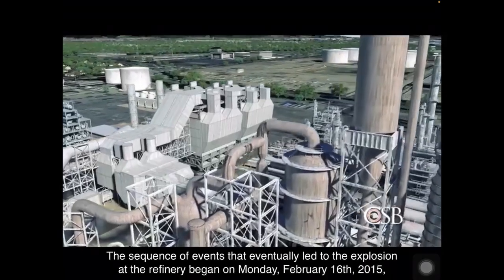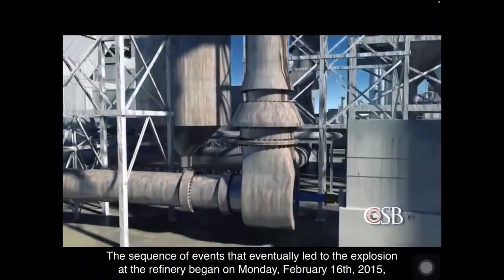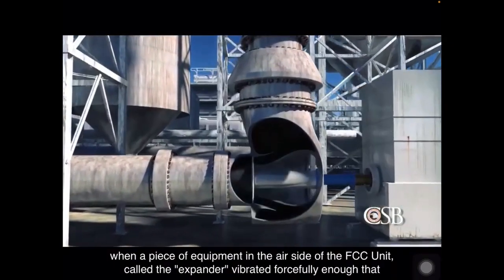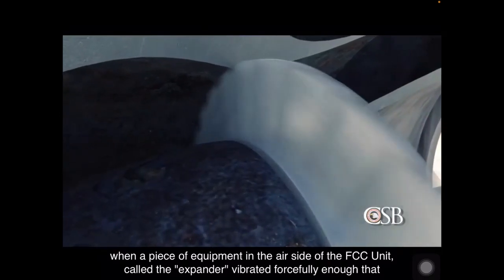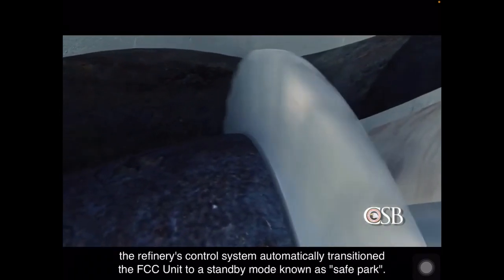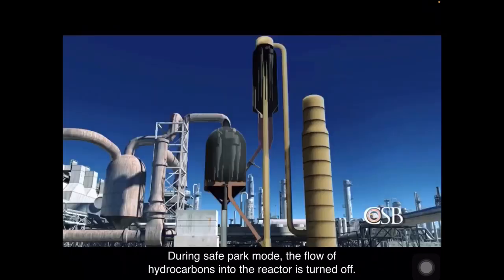The sequence of events that eventually led to the explosion at the refinery began on Monday, February 16, 2015, when a piece of equipment in the air side of the FCC unit, called the expander, vibrated forcefully enough that the refinery's control system automatically transitioned the FCC unit to a standby mode known as Safe Park. During Safe Park mode, the flow of hydrocarbons into the reactor is turned off.